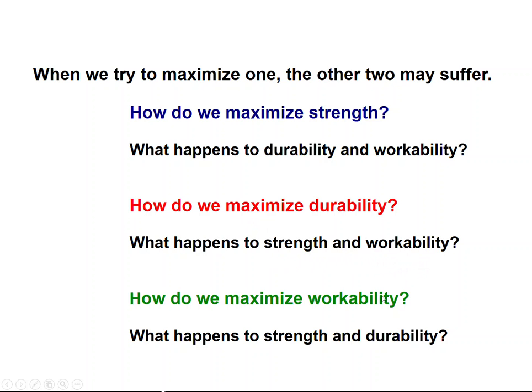And same if you're a worker, right, a tradesman, and you're the responsible for working with the concrete as it's delivered on site, you care about workability. You want it easy to work with. Well, you might not care about the strength and the durability of the final product, but ultimately, potentially lives of people will be dependent on those two properties. So what happens to them when you ask the concrete delivery truck to add another couple gallons of water because you want it more workable?